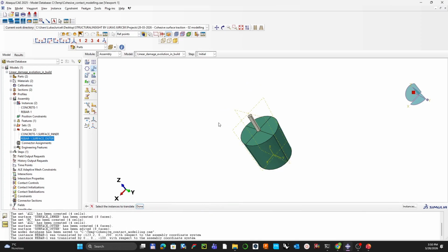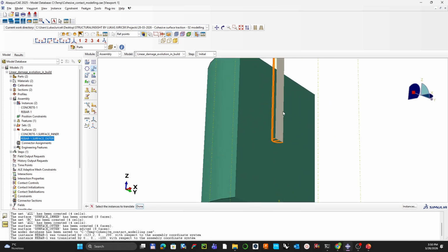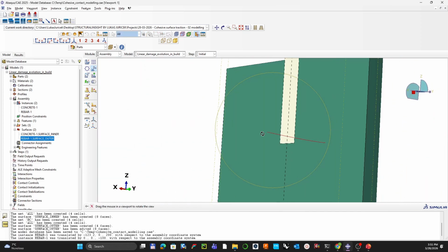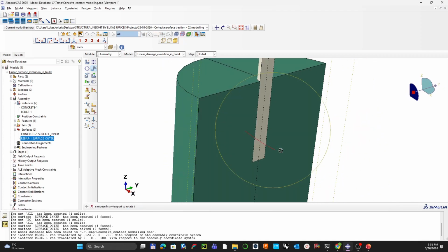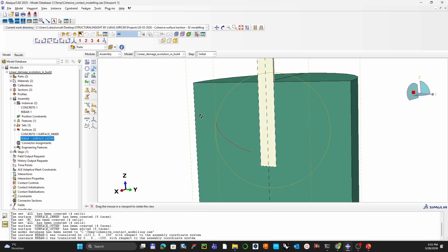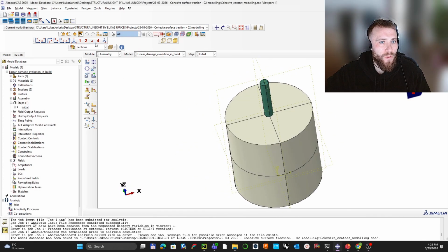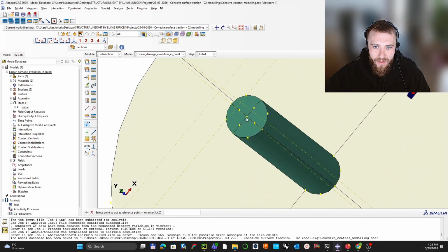Once you do it, you can just confirm, and to validate that everything is passing, I can just move forward inside and double check if my interface is passing and nothing is overlapping, or if some gap has been diagnosed. Okay, so we just finished up the assembly and we can move forward to the interaction. In the interaction, I will just need to set up the reference point. The reference point will be aligned with the center point on the rebar.